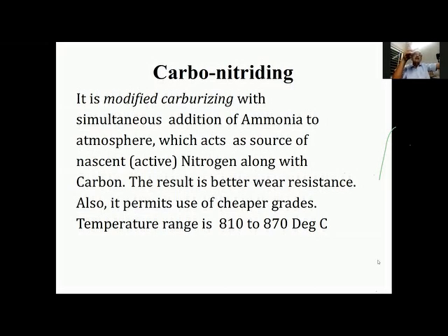And where do we use carbonitriding? Where you need slightly better wear resistance. Like if I have a gear which is going for a tractor or earth moving equipment, those are heavier cases. Case depths are more. There you need high temperature to have it in the lower time.